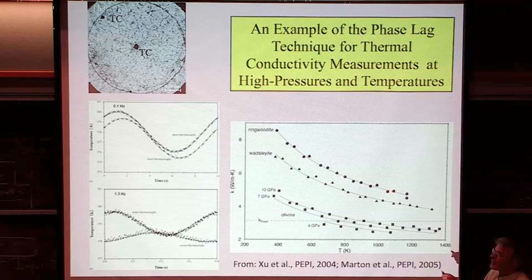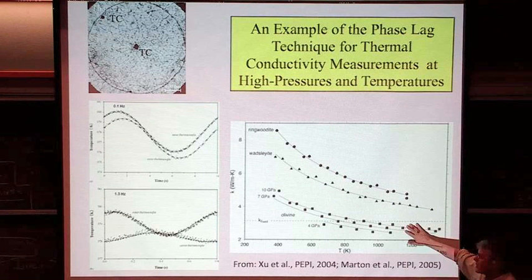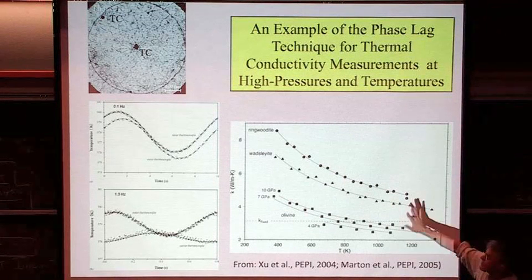And the reason there is a distant correlation with structural complexity is you can imagine that the nature of vibrations in the material depends on the complexity of the crystal structure. So there's a tandem effect of increasing density on the thermal conductivity, but also a trend of complexity, which is basically what the vibrations look like in each material, and they're simpler in a simpler structure.